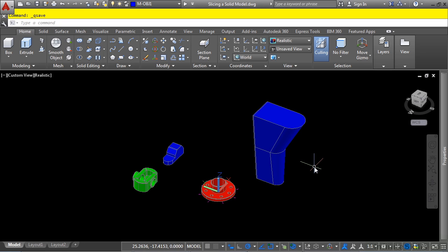The slice command allows you to slice material away from a solid model or to split models into two separate pieces. This capability is especially useful when you want to bevel a model and the tangencies of the model edges prevent the chamfer command from achieving the required results.